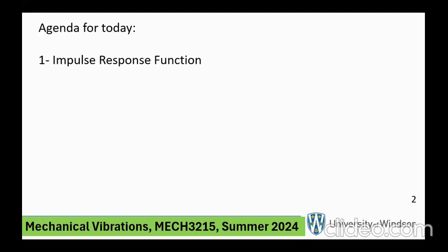For the past 3 weeks, we came and said, okay, what if the right-hand side is not 0? What if actually there is a force acting on this mass under consideration? Remember, we are looking at single degree of freedom systems. In that case, the mother of all equations, of course, becomes m x double dot plus c x dot plus k x equal to f of t, whatever that force happens to be.